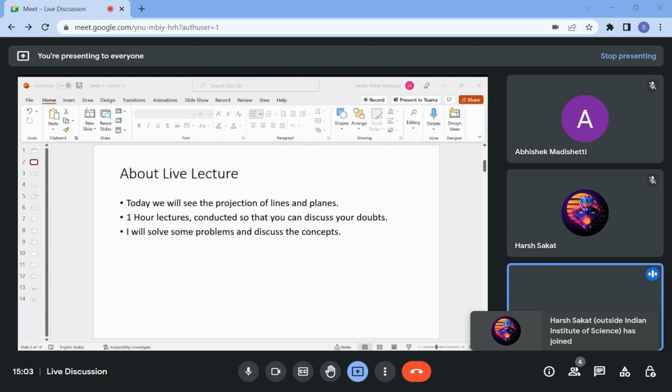If I keep the angle with the horizontal plane constant and change my angle with the vertical plane, I trace a cone similar to the one shown here. Let us fix point A at 30 above HP and 40 in front of VP. Then point B is going to trace this circle.